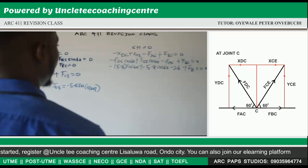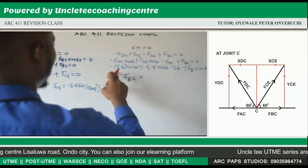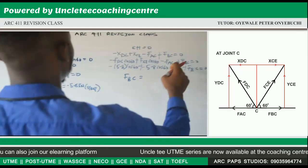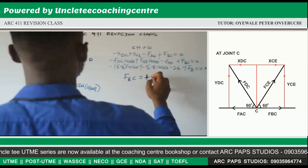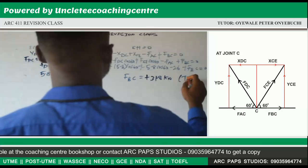Now when you solve this, our FBC will give us, using your calculator, minus 5.8 cos 60 minus 5.8 cos 60 minus 26. That will give us minus 31.8. Taking it to the other side, that will be plus 31.8 kilonewton, which is a tie.